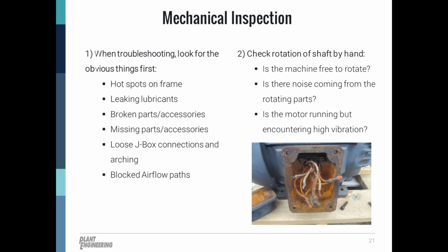As we touched on earlier about motor enclosures, it's always a good practice to look for blocked airway paths. For example, a TEFC motor. There are a lot of applications that can cause the fan cover vents to get blocked from materials in the environment. So for example, damp paper or sawdust particles, rock dust. There are so many different contaminants that can produce cooling problems.